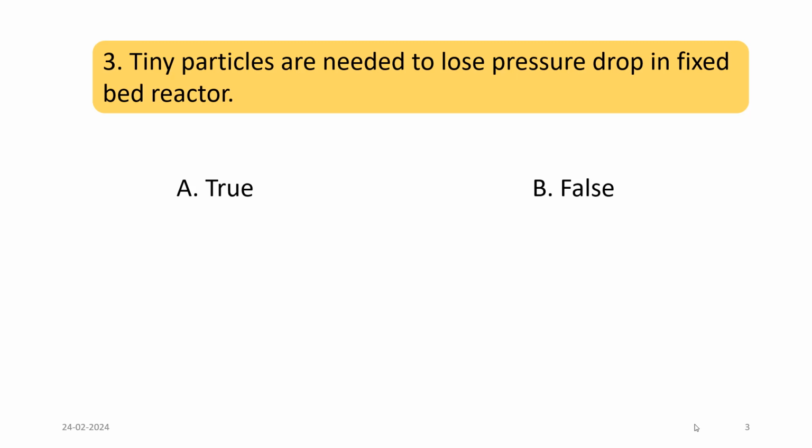True. No, it is not true, because in case of tiny particles, what happens? The particle size is very small, so their surface to volume ratio is very high. So for that case, they have high pressure drop.